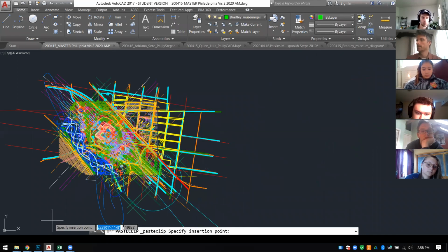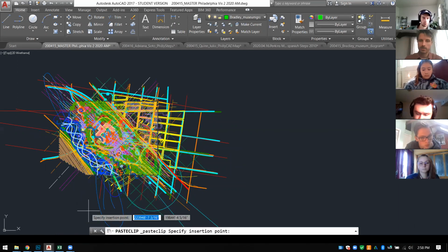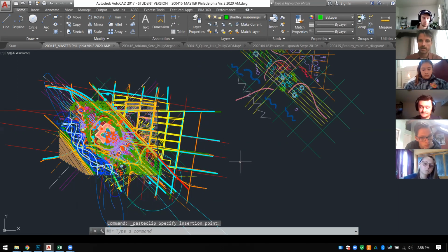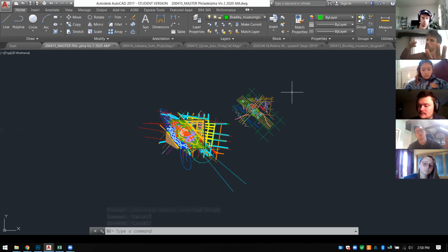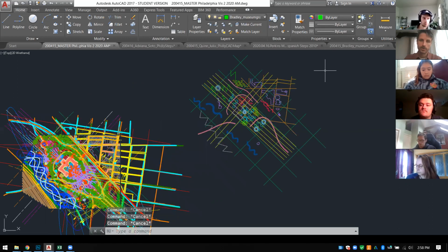And the problem with eyeballing it is then, let's say a bunch of people outline the art museum. So I've got 15 different versions of the art museum, which is the right one? So you really want to insert with a base point. And if you connect to the wrong thing, then we have an inaccurate drawing. The objective is basically to peel off the layers from your drawing, move them over, and put them down in a new drawing. Okay? So here's what we're going to do.